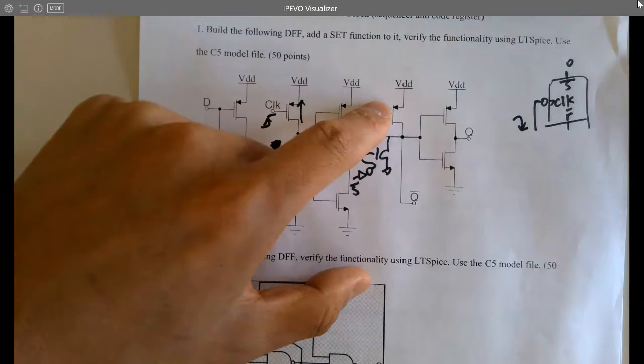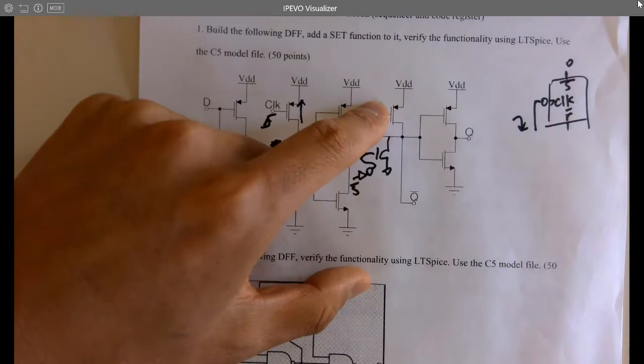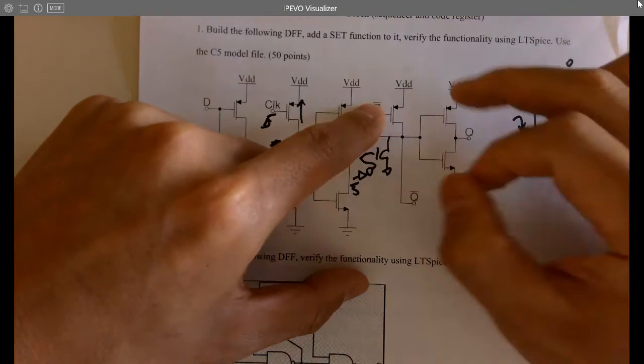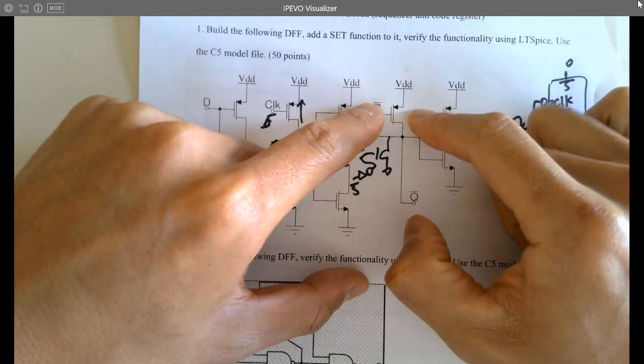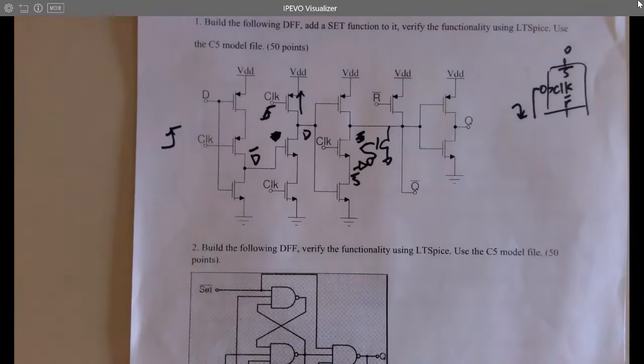Because according to the square law equation, it's W over L, right? For a stronger transistor, you need W to be bigger. So it's going to be a big transistor, wider. If you think about the layout, a wider transistor means it's longer or wider? It's just a trap. I know you are going to jump into it. During the layout, you have the rail-to-rail, and the transistor in the middle. So for a wider transistor, is it going to be longer or wider? Longer.